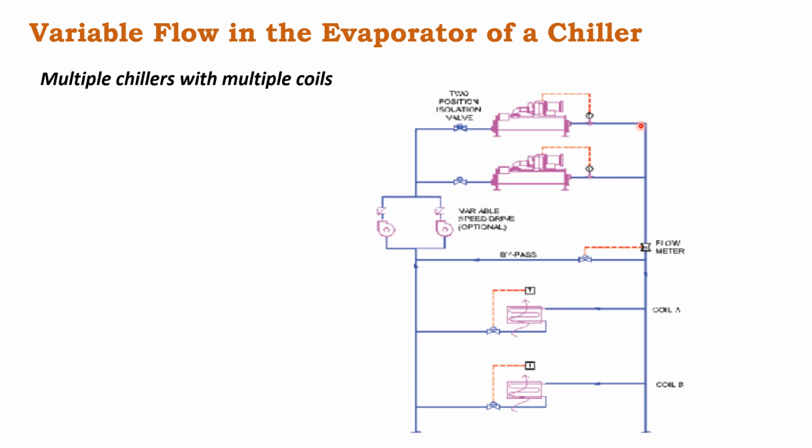the excess pressure drop in the network when the system is working at minimum or part load or less load. I can even provide it over here also, but then the pump is going to put out excessive pressure and consume energy to overcome the frictional losses over the network. If it is installed over here, this is the shortest and closest loop and is going to add great energy efficiency to the system.